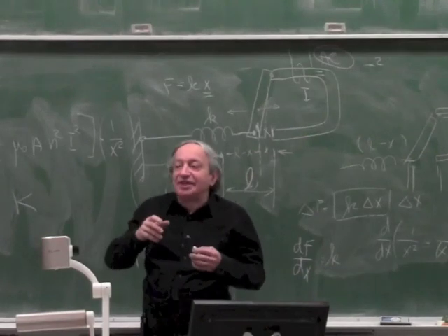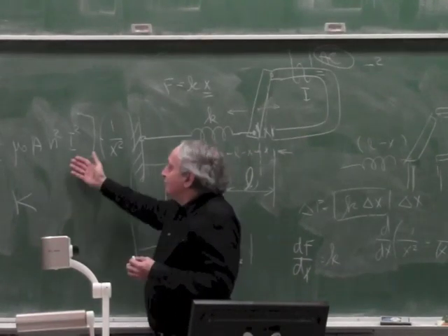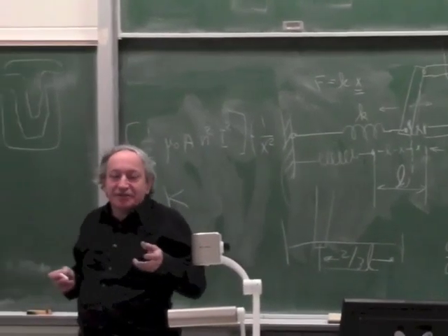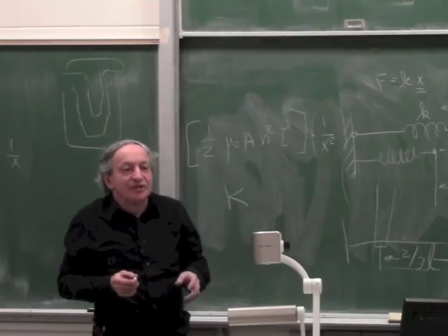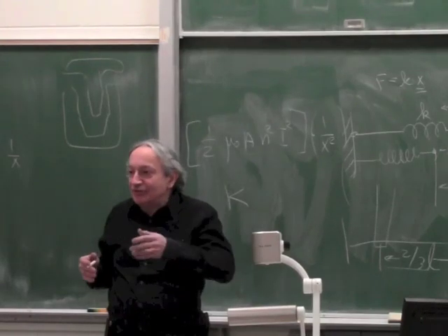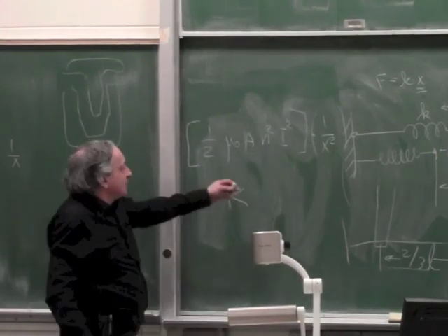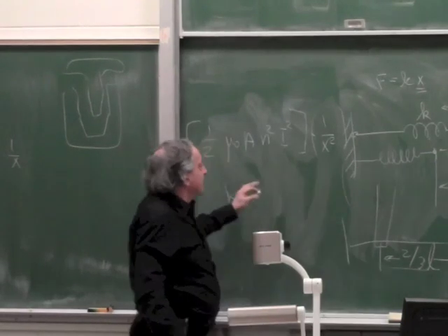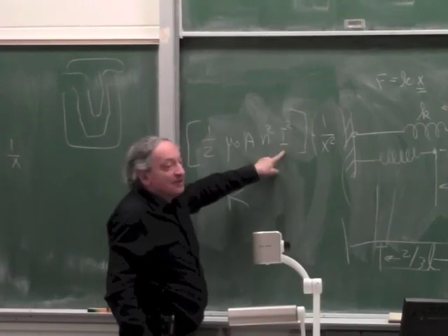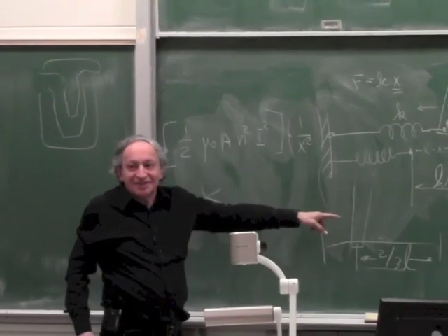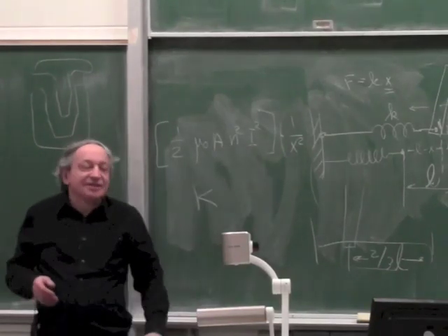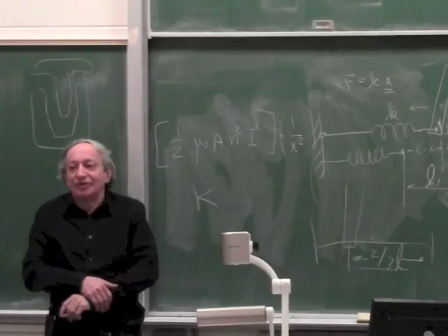Okay, so now you have a good hint that in a DC actuator I is changing, say, slowly. Here I must be changing faster to counteract this. So in other words, when I increase the voltage on the actuator, in a DC actuator, I is changing linearly. I double the voltage, I've doubled the current, because it's simply V over R. But it seems that in an AC actuator, if I take the same circuit and run it on AC, when I double the voltage, it seems that I doesn't double. Otherwise it'll behave the same as DC. It seems that when I double the voltage, I goes up much less than double. And this counteracts the behavior of 1 over x squared.